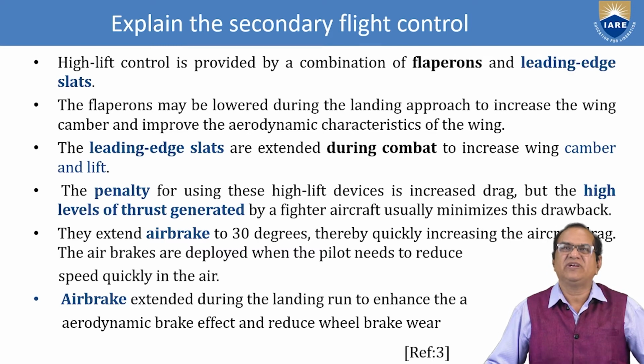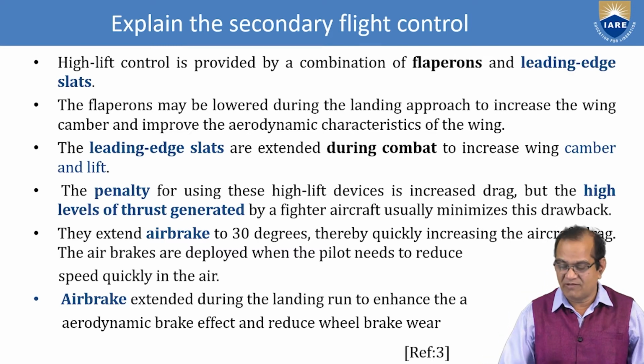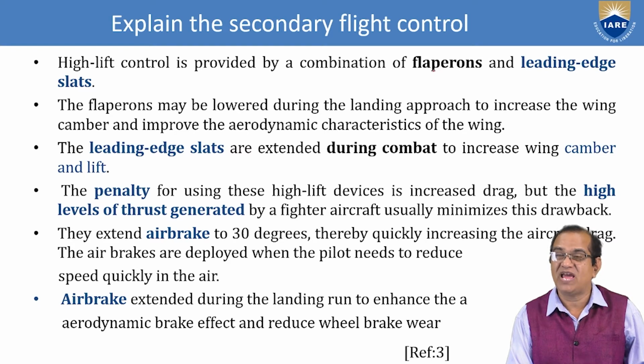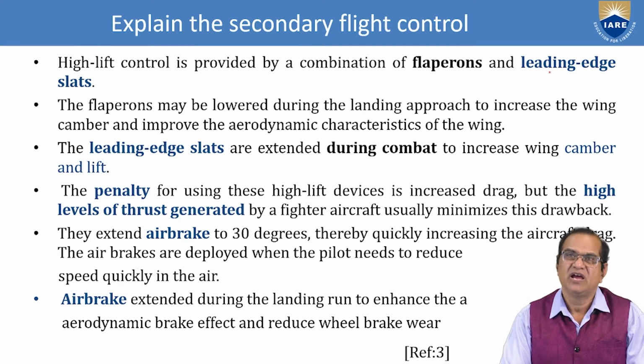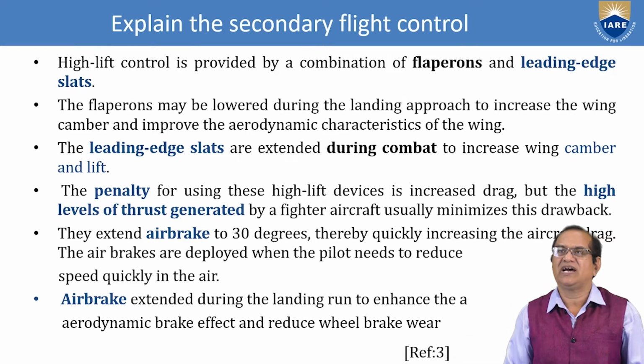So this high lift control is provided by a combination of the flaperon, meaning flap and aileron, and the leading edge slats. The leading edge slats are on the wing leading edge, they are fixed. Flaperons may be lowered during the landing approach to increase the wing camber and improve the aerodynamic characteristics.